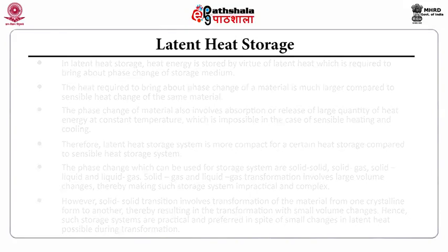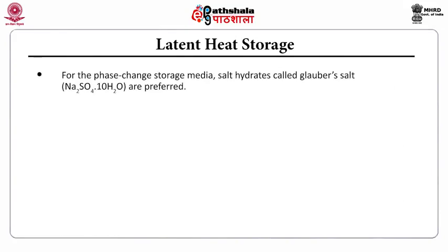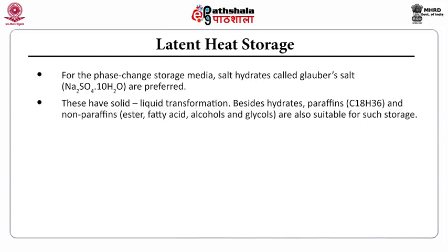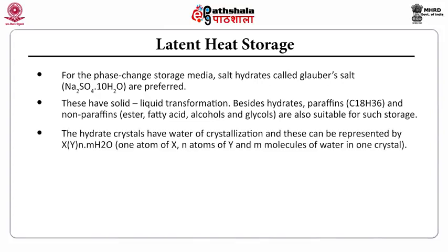For the phase change storage media, salt hydrates called Glauber's salt, that is Na2SO4·10H2O, are preferred. These have solid-liquid transformation. Besides these hydrates, paraffins and non-paraffins like ester, fatty acid, alcohol and glycols are used for this storage. The hydrate crystal has water of crystallization and can be represented as XY_N·MH2O. That is, one atom of X, N atoms of Y and M molecules of water in one crystal.